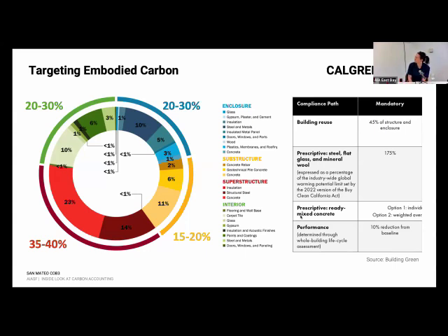So the key is it's going to take conversation, right? Those questions of the simple, there is no cost if you go to a certain percentage limit. That talks to, again, the opportunity for the design team, the engineers to have those conversations directly with the manufacturers, with the contractors to say, where is that limit? We often talk about it from a cost perspective, right? If I have a 10-foot 2 piece of glass versus a 10-foot piece of glass, there literally is a cost difference for 2 inches. Did you really need that 2 inches? It's a similar conversation as you're trying to reduce carbon. Where's the limit? Where is it really a premium starts to happen? What's the trigger point in the fabrication process?